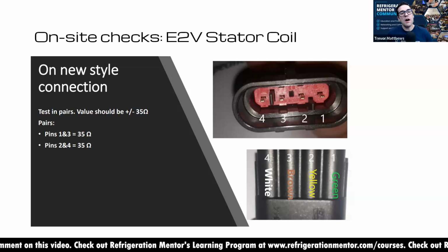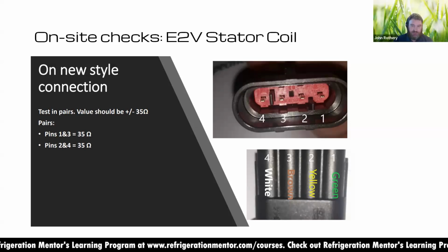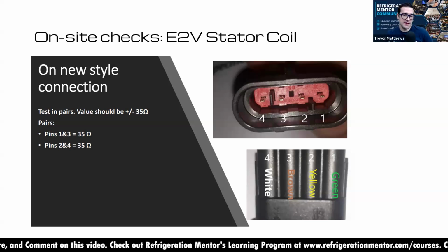And what could cause a stator coil issue? What have you seen in the past, John? They can short out over time. They're sat on the valve, so they're getting cold and they're in a moist environment. They can fail and stop driving. I've definitely seen, not this specific one, but unhooking them from the valve and they're all rusted inside because of the moisture.